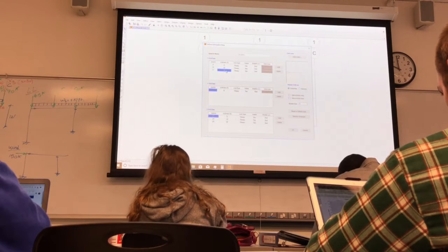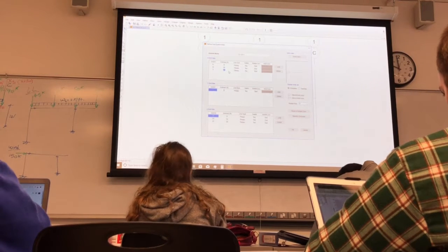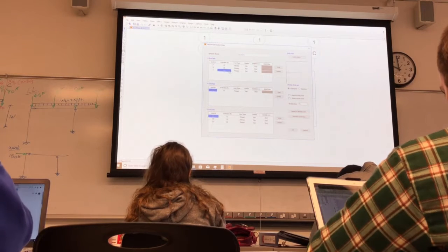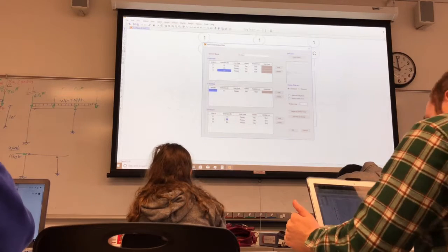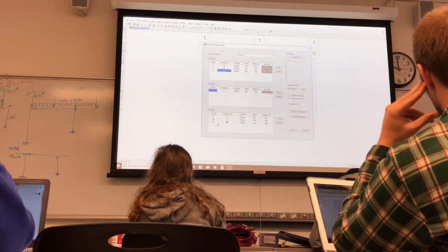All what I need to change is these numbers. I can change 48, which is X3 or C, change it to 30. And then for the Z, I need a grid at 6, and I need another one at 18, so I'll just put here 6 and 18.